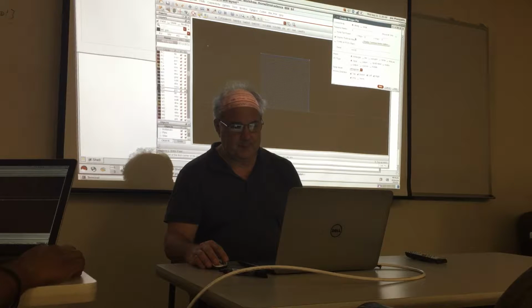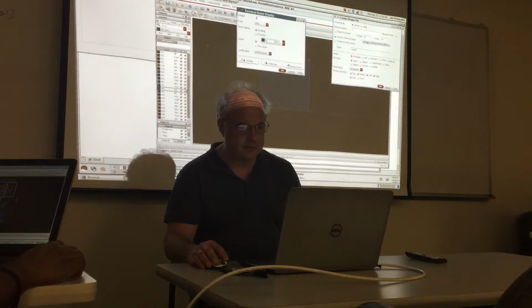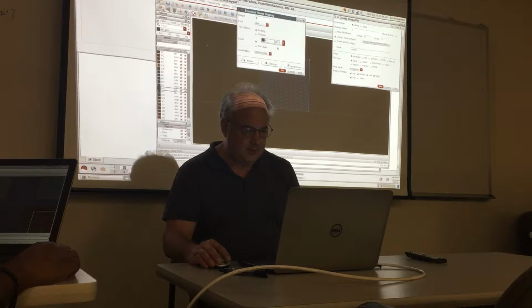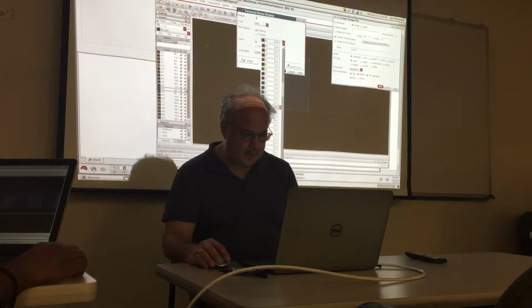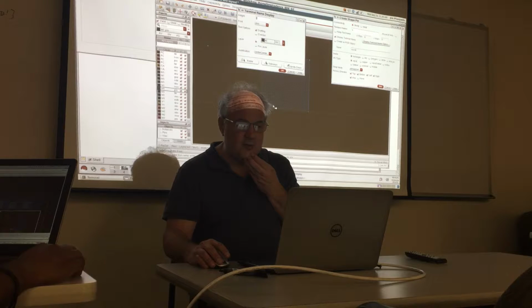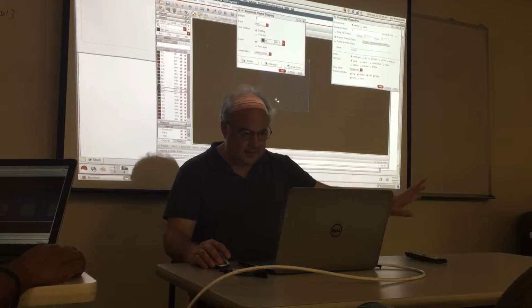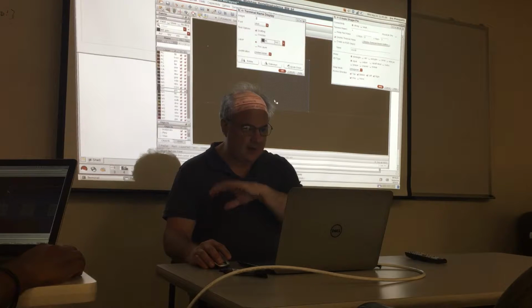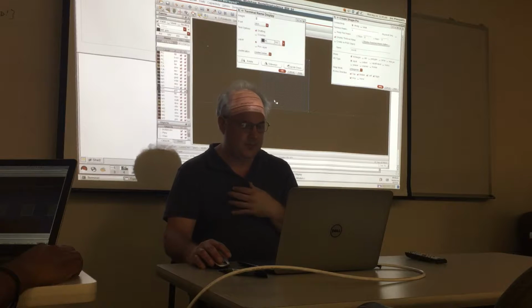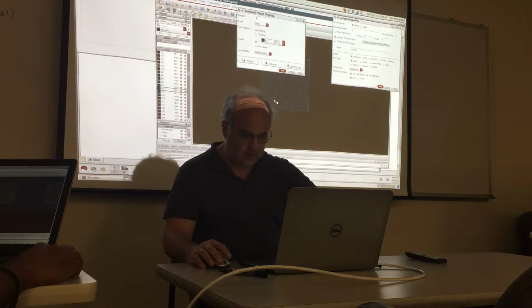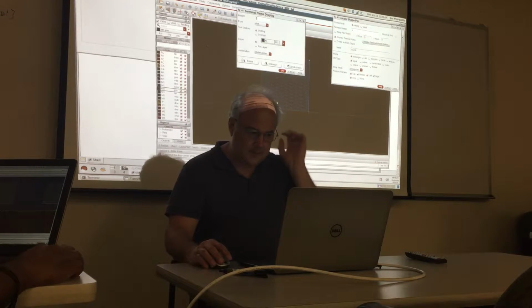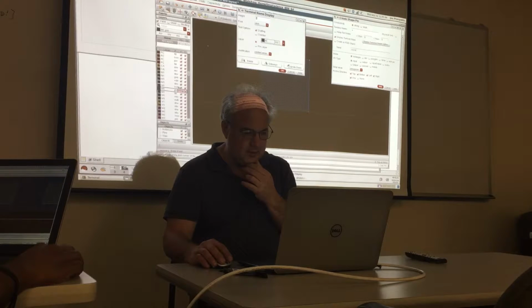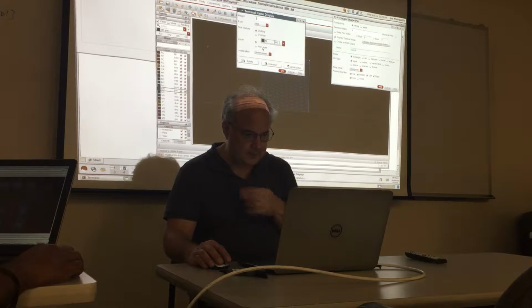Okay, and then give it a name, right? And then go to this display name option, and it remembered it. But normally this is not set properly, so you have to choose the LBL for the metal layer that you're drawing for. Some of them use just generic, like, label. IBM's PDK has an LBL for every pin layer purpose pair, and you'll see the variation here. Sometimes you just have an LBL in the layer menu over here that you would actually use, but you want to use this one for this PDK.